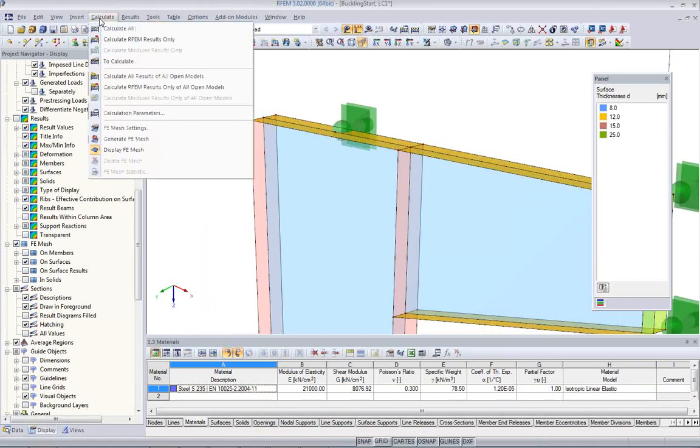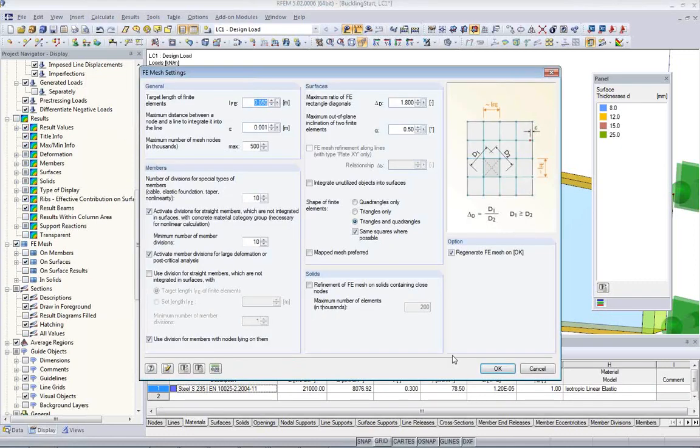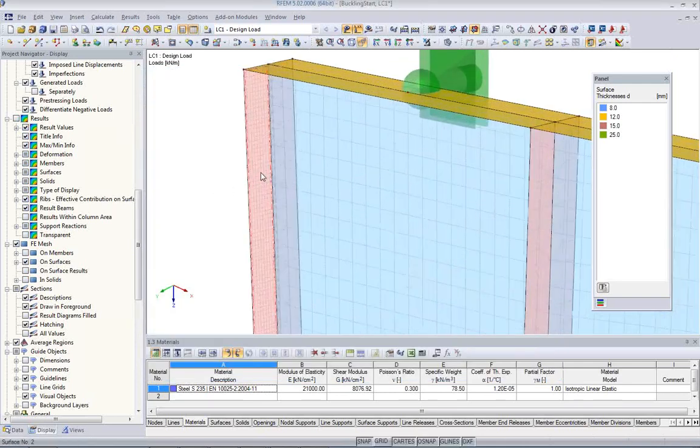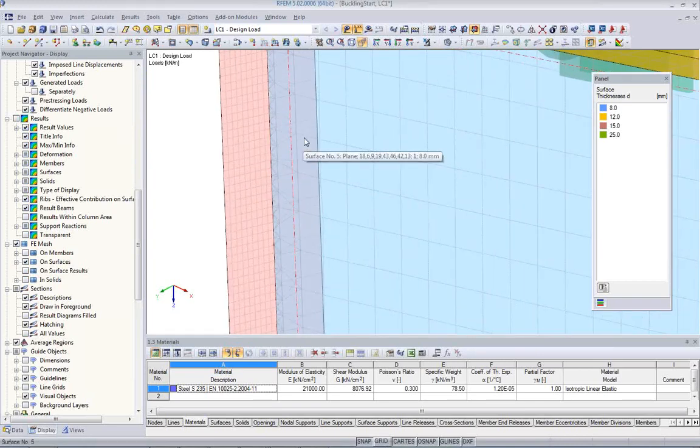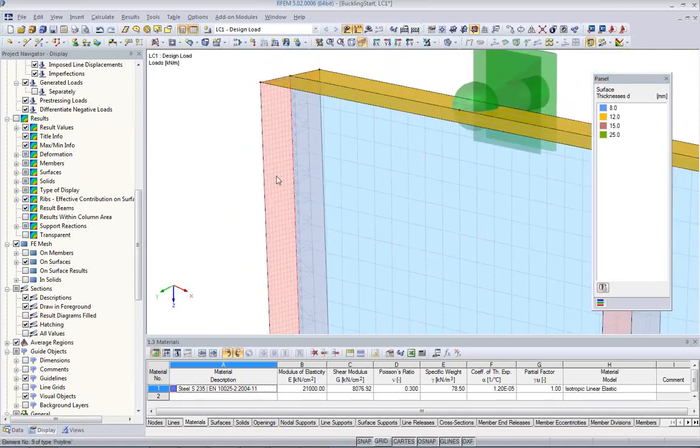And once I create the finite element mesh, or I click on OK, it takes a little bit longer now to create that mesh. And of course, you have a very fine mesh here now, and the transition from the rough mesh to the finer mesh is done here over certain cells of the mesh, which is, well, better. So we have some smooth transition from the coarse to the finer mesh.